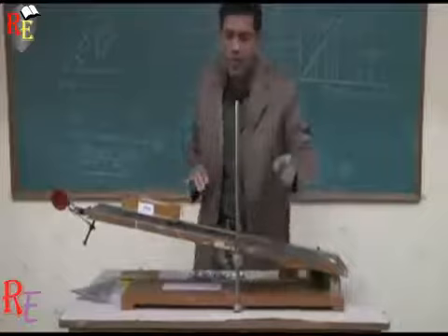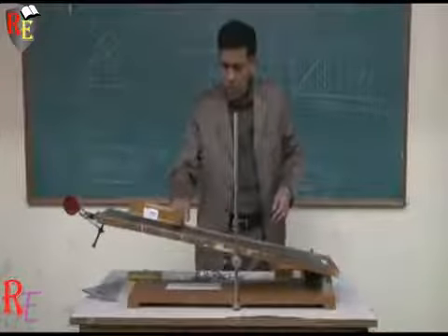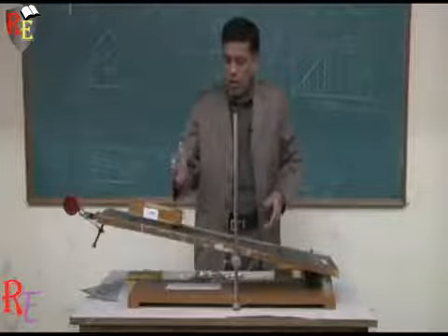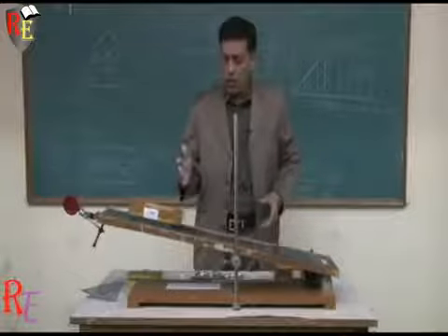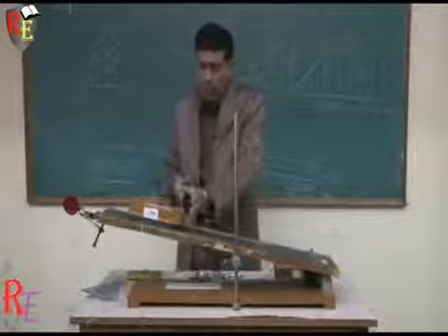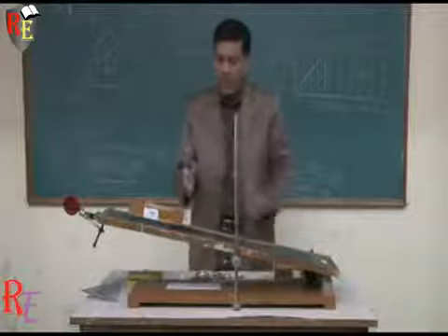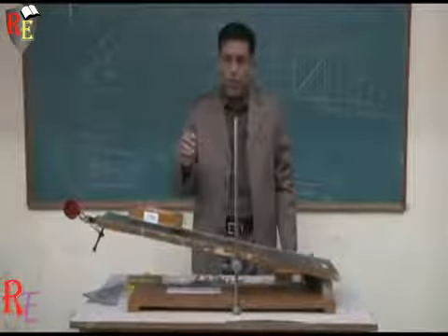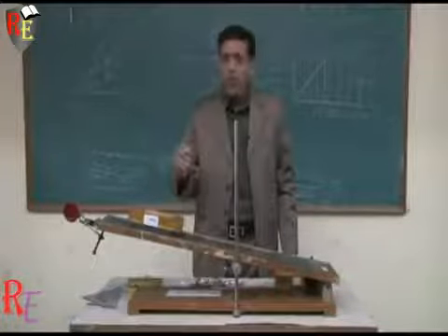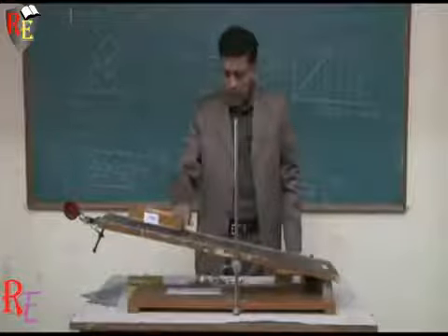So I would change this angle of incline, and then I tap it. And this process would continue until the limiting condition does not exist. Limiting condition means that the block is just about to move, on the verge of the movement. Okay, impending state. It is worth mentioning that in case of the impending state, the block would just move and then it would stop. Okay. So I would tap it.